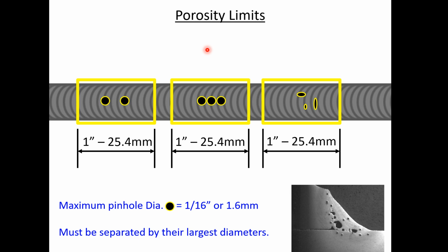Once you have a discrepant weld, whoop, what's different about that? Now it's time to define whether the weld overall just has a discontinuity, or whether the discontinuities keep adding up until we have a defect. Within the standard, it always says 1/16. I don't know a standard that allows anything bigger than 1/16. I know standards that say they allow nothing, but there's a lot of conditions that go around that, and very, very seldom do they ever come up.